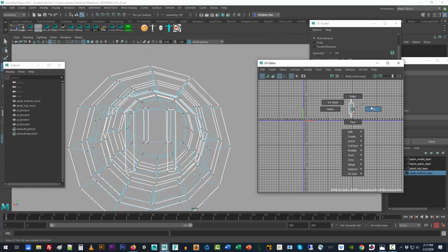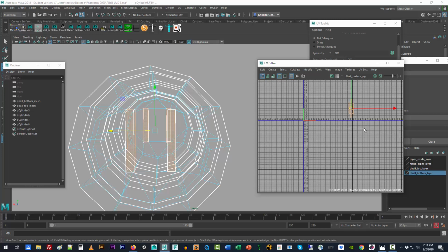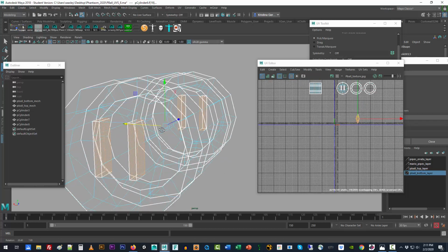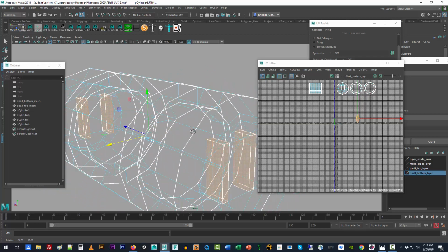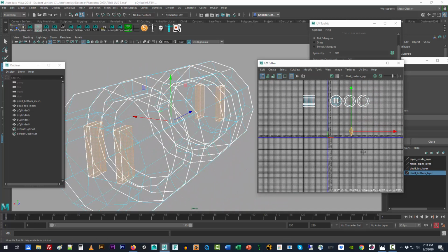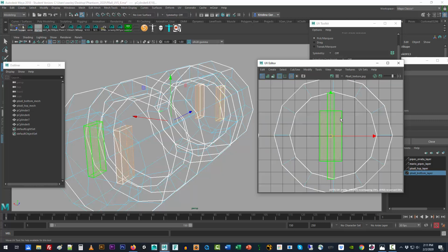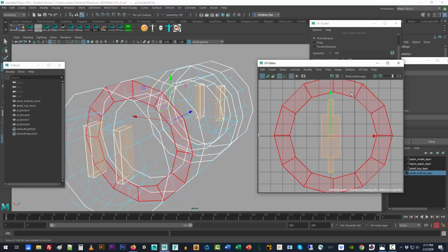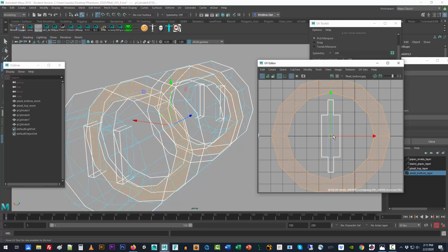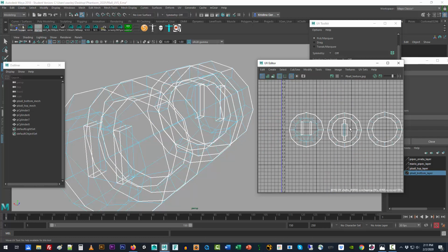Each one of these UV selections is right on top of each other, including all the interior adjoining walls. And that lets us bring it up, and you can hold down the X key if you want, into the middle of one of these ringlets for all of the faces. And I'm going to scale it down just a little bit more. There we go. In fact, what we can do is just hold down the X key, snap it to a grid, grab these, snap it to the same grid, and it'll align them perfectly. So that's a little trick you can use to line things up.